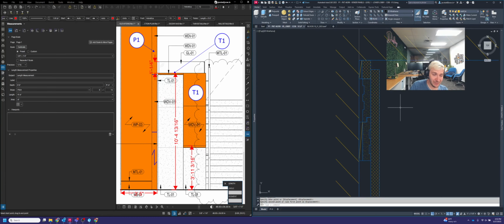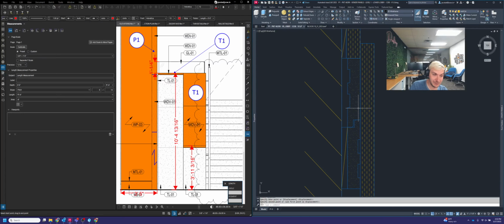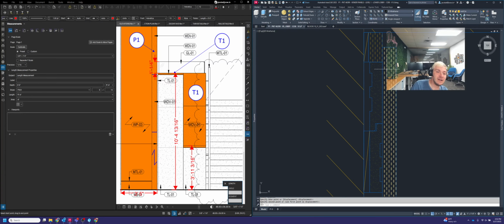When you go to put these in behind your panel, one thing to remember is you can't actually put it in just like this. You do need to have a small gap between that full depth reveal and the top of the first cleat. The reason is if you just put the cleat in here like this, there is no lift-off space because this cleat is screwed into the back of your panel.